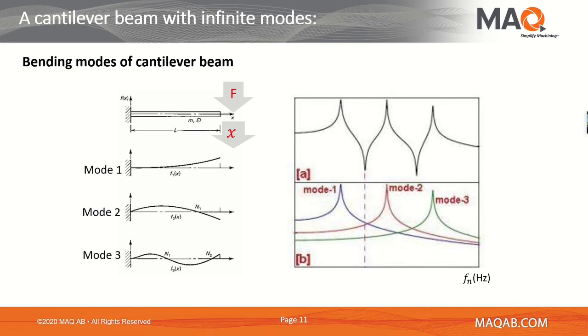And if you look at a cutting tool, this is a very typical cantilever beam structure, mostly in bending motion. If we apply a force on the cantilever beam and change the frequency of the exciting force and look at the displacement, the same cantilever beam can be excited by many frequencies. So it has a few more frequencies than what we thought, where the structure can be easily excited. And we can imagine this cantilever beam as composed of thousands or millions of small springs and small masses connected with each other. That's why we can see several modes, or plenty of modes, in the same cantilever beam structure. It is actually true that a cantilever beam structure has an unlimited number of modes, and it only depends on the frequency range that you can do analysis with.